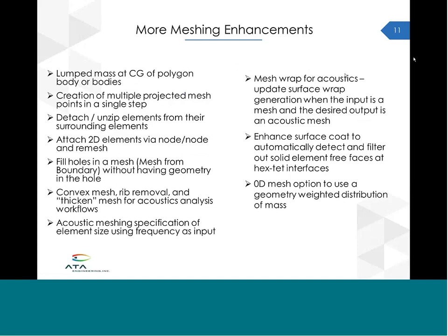There's a new enhancement to create multiple projected mesh points in a single step. I also like that one because that used to be a fairly tedious manual operation if you had a number of target points or geometric points that you wanted to project onto a surface to create mesh points to drive or force the creation of nodes during the meshing process. That's now much more straightforward.